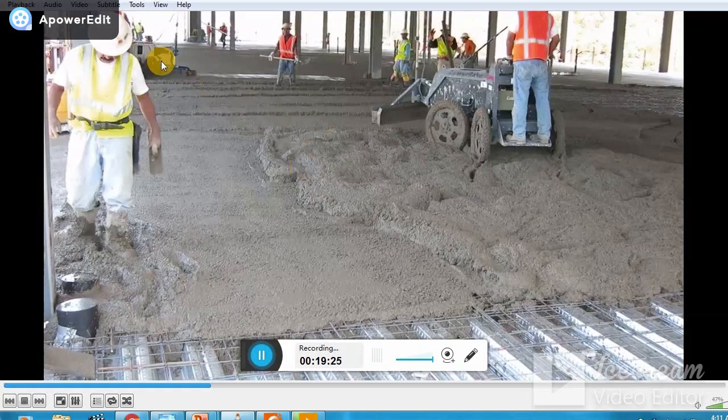Once this concrete is covered, after 28 days, the live load then comes. So we basically design before 28 days and after 28 days. Once we make the analysis of the composite section, we basically do the analysis for both of these two stages.